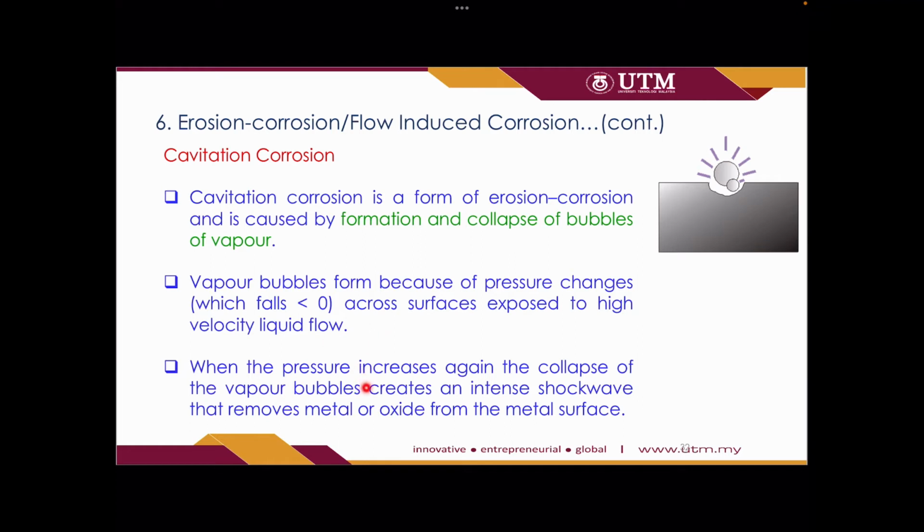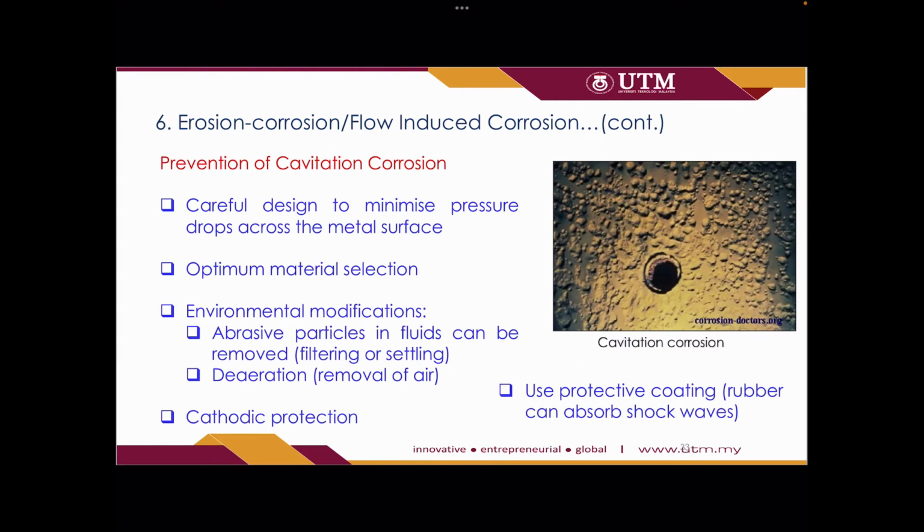So when the pressure increases again, the collapse of the vapor bubbles creates an intense shock wave that removes metal or oxide from the metal surface, okay, just because of these bubbles only, due to the changes of pressure. So how to prevent cavitation corrosion?